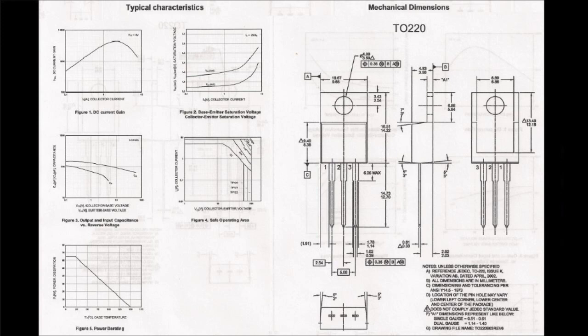It will also show you your DC current gain. It shows you your safe operating ranges, and it shows you how your transistor will derate on high temperatures. And when you're testing transistors, these charts will give you an idea of how this transistor should perform.